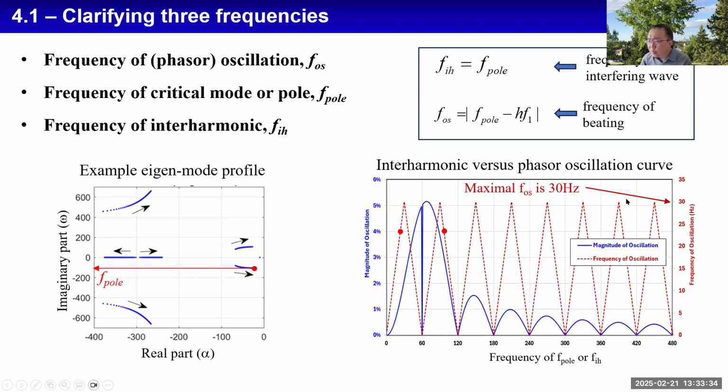This is similar to the Nyquist sampling theorem. Basically, the phasor is defined for each cycle. So that means in 1 second, we only have 60 data outputs for the phasor, 60 data points per second. Therefore, we are essentially sampling 1 second of data using 60 samples. Therefore, the highest reporting frequency is 30 Hertz, similar to the Nyquist sampling theorem. That's why we have this maximum 30 Hertz reporting.